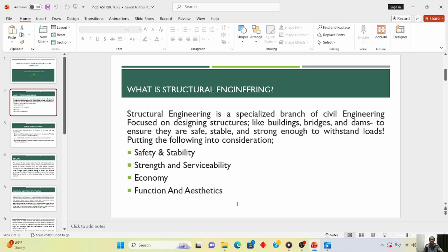Okay, the design actually said 12 mm reinforcements for the solid slab, and then during execution, 10 mm was used. It shows that safety was not considered, and that could be a great issue for the structure, meaning the structure is not safe.